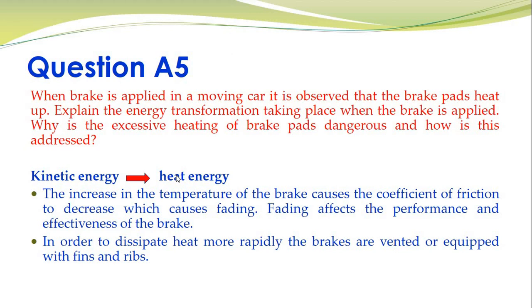Now it says, why is excessive heating in the brake pads dangerous? We know that there is a phenomenon called fading, and fading is simply the decrease in the coefficient of friction due to the increase in temperature. So when a brake fades, its performance is severely affected. At a higher temperature, the brake loses its characteristics, it loses its coefficient of friction, so it's not going to provide effective braking, and this can lead to dangerous situations.